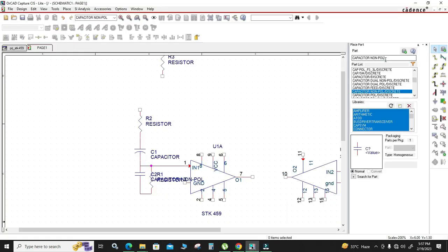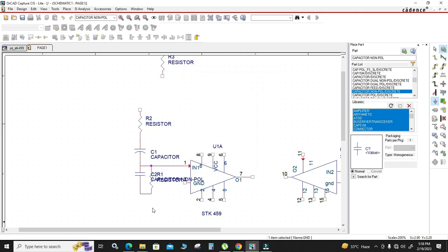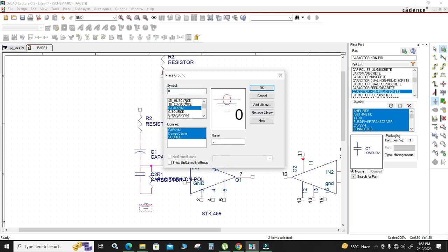Instead of searching for the power supply, here we can see a toolbar in the palette. There is a power option in the palette. You can see this is a ground icon, or you can press the G button and choose this one. It has many symbols for the power supplies and ground. So I'm choosing one, this is for perfect ground. Then I choose one here. Then the same, choose this one again. Then choose one source.